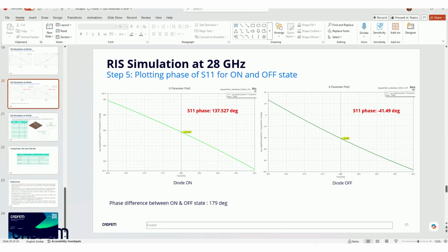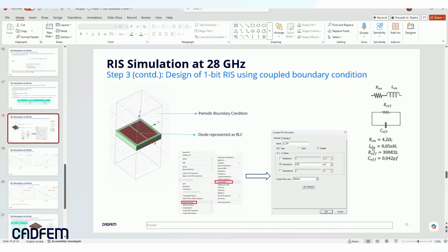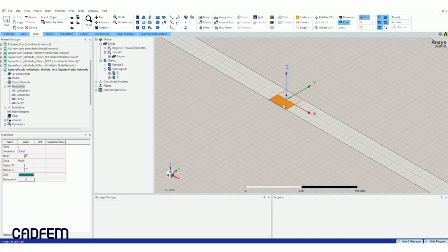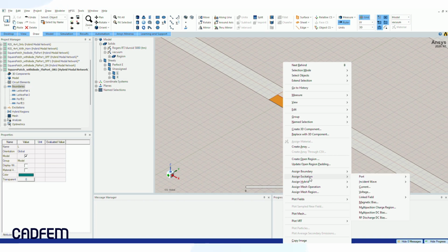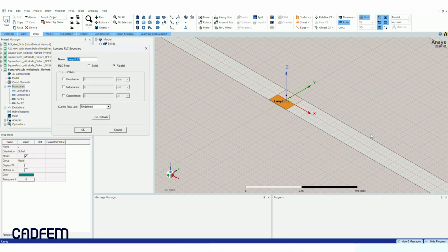complexity into the simulation. Before launching the full electromagnetic solver, we execute a rigorous validation check under the Simulation tab. This steps through our 3D design, boundaries, excitations, and mesh link setups. With all design variables successfully validated, we can confidently click Analyze All to initiate the high-frequency electromagnetic sweep across our targeted band.